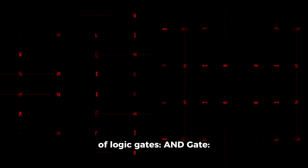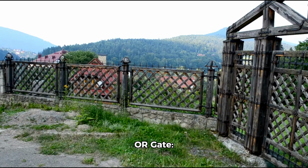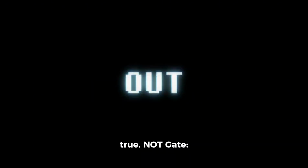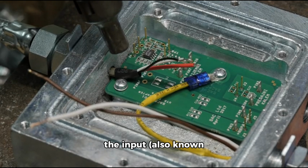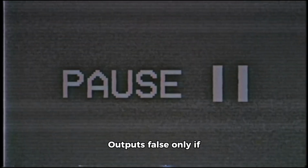Here are the primary types of logic gates. AND gate. Outputs true only if all the inputs are true. OR gate. Outputs true if at least one input is true. NOT gate. Outputs the inverse of the input, also known as an inverter. NAND gate. Outputs false only if all the inputs are true, inverse of AND.